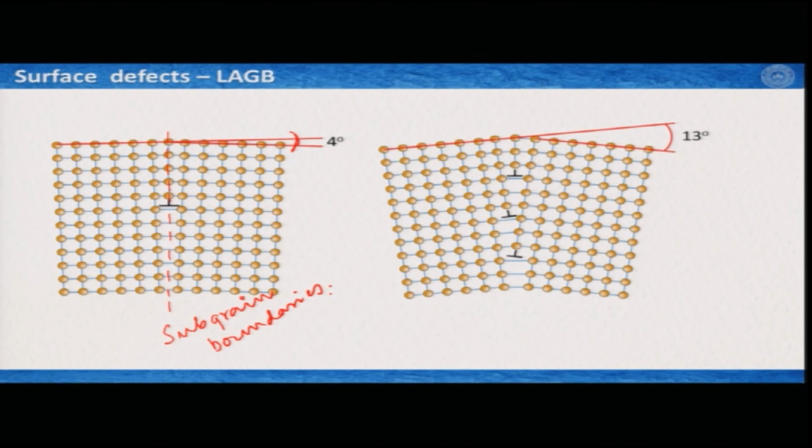Where the angle between the two grains is very, very small. And here, this is also a subgrain boundary, with higher grain boundary angles. And what is important is that this could probably be your grain boundary, and these grain boundaries are marked by dislocations. If we have dislocations at the grain boundaries, that means the grain boundaries are also a storage, or places where you can find more and more dislocations.